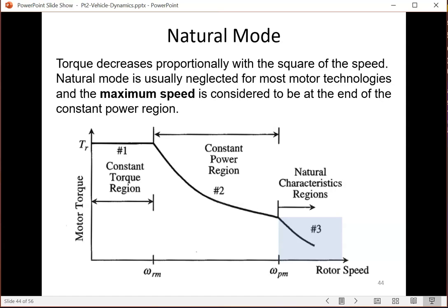Okay, that would be a limitation or constraint for driving vehicles, because at a high speed you will need to at least be able to produce enough traction force to overcome the rolling resistance, and in particular the air drag. So going down is not really a particularly good idea.